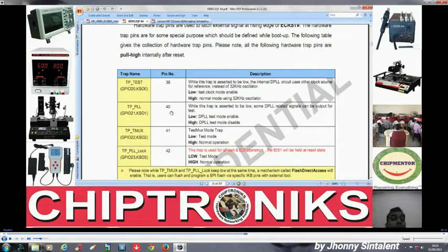Here we are talking of this IO controller. We are not talking that this IO controller is used in this laptop motherboard. We are talking of universal. So a data sheet will mention universal things. That's why they have written that this pin number 39 may be used as a GPIO pin, GPIO 20 in some motherboards, or maybe used as keyboard scan out 0, or keyboard scan out 1, or as GPIO 21.